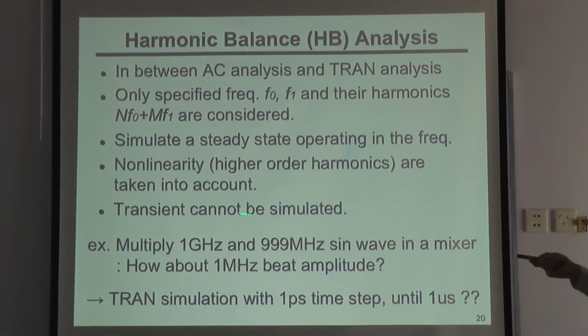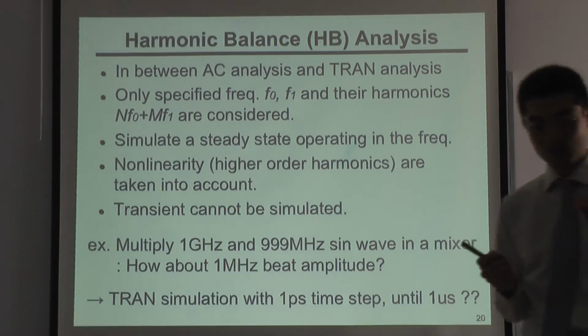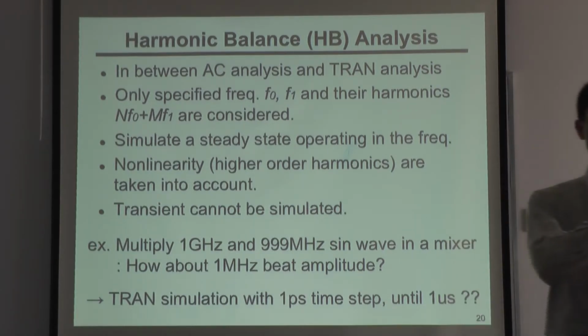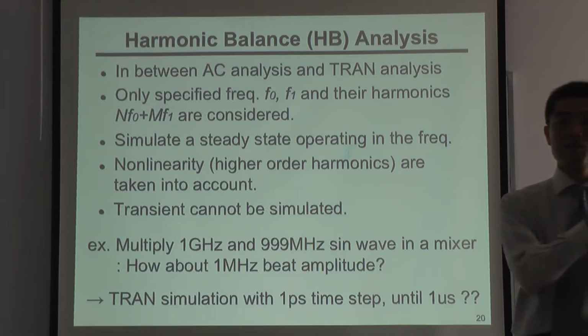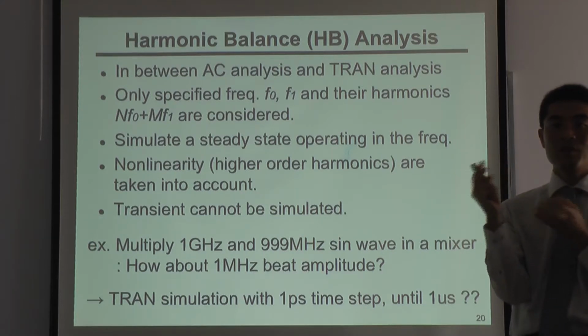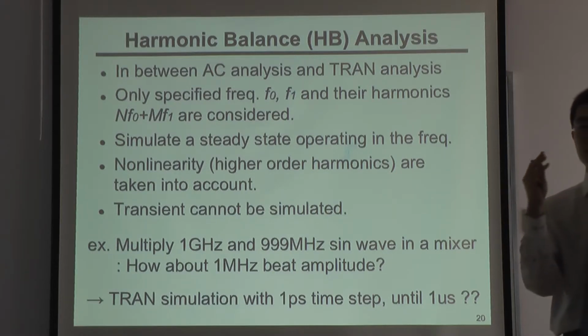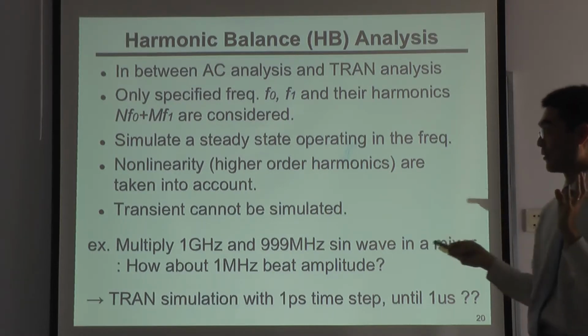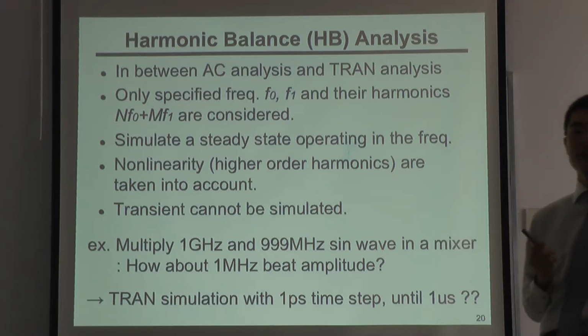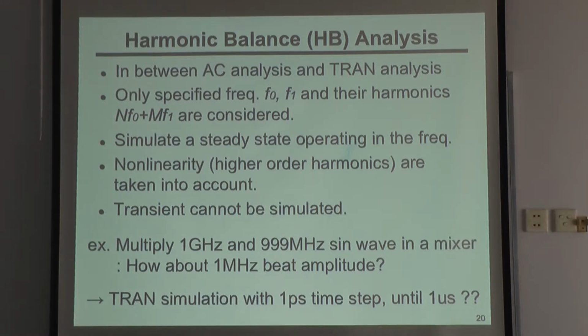And transient cannot be simulated means the startup transition cannot be simulated. It's only simulated in steady state. But steady state does not mean DC. It's in AC, and the steady state operating conditions can be simulated by harmonic balance.